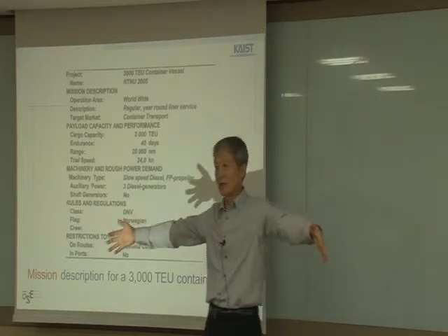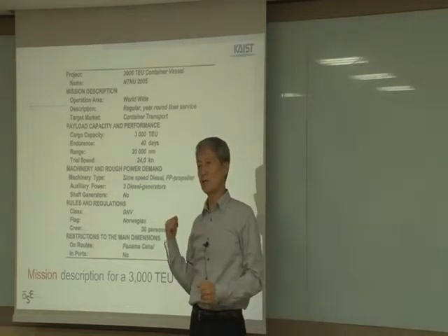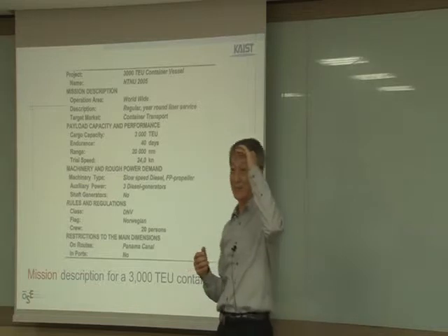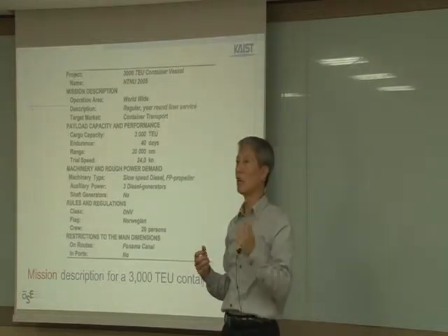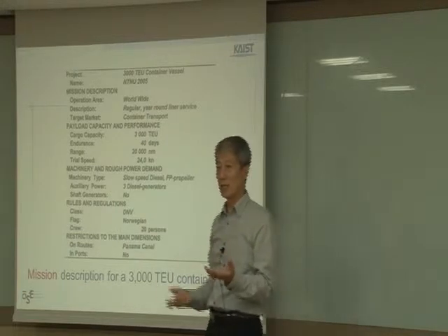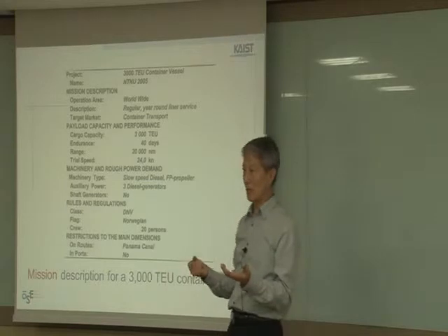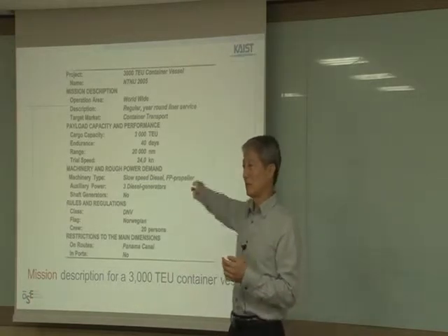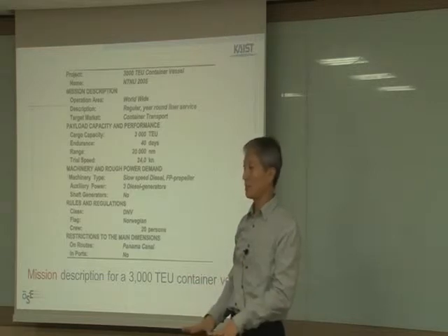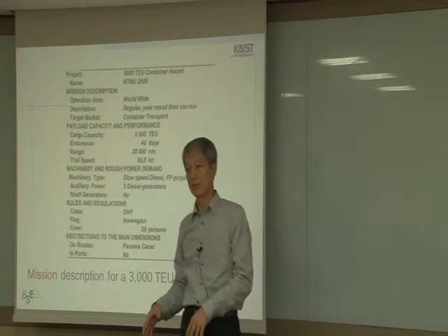A big engine is okay. Why do we take a slow speed diesel engine in a ship, even though it is big and heavy? Because the efficiency is high. And also they can take a low grade fuel, the cheaper fuel, right? Compared to my car, gasoline is a high price. The slow speed diesel engine takes a low grade fuel oil, and it is very cheap, right?